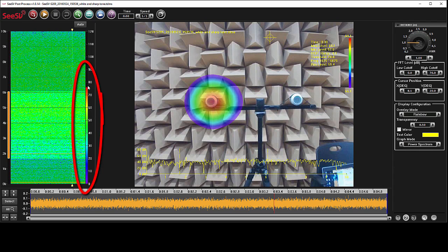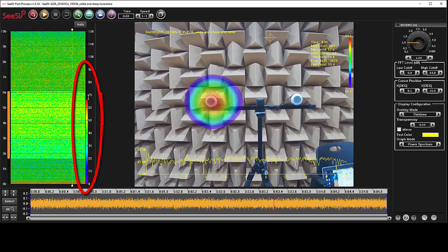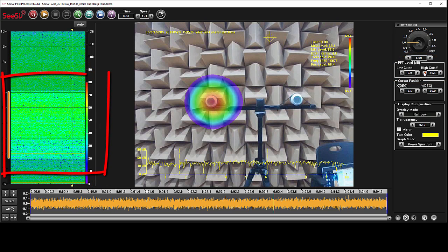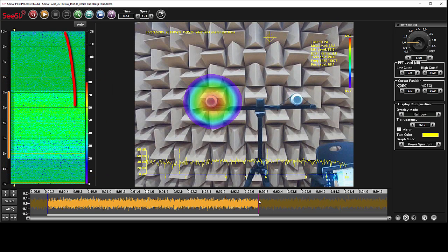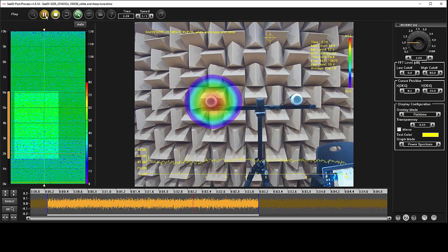This legend indicates and controls beam power intensity in the spectrogram. It can be adjusted without affecting beamforming in the main display. The value can be changed by dragging the bar on the spectrogram or numerically through FFT level section in page 2 of the settings. The highlighted part is to show the selected playback time and bandpass filter. When the video is being played, the yellow line with the indicator on top and bottom shows the lapse time.